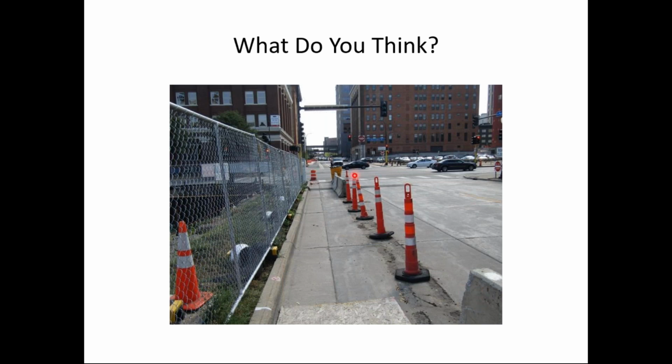So this is one of the challenging problems. I'm not proposing they should put the concrete back here for just a few hours, but yet they do need some sort of detectable surface. Maybe pedestrian channelizers that could be relatively easily moved out of place when the trucks return the next morning. But it's going to depend on probably more than what we see here. The point is, what you see here is not an appropriate pedestrian channelizer, and it's not safe for motor vehicles either.